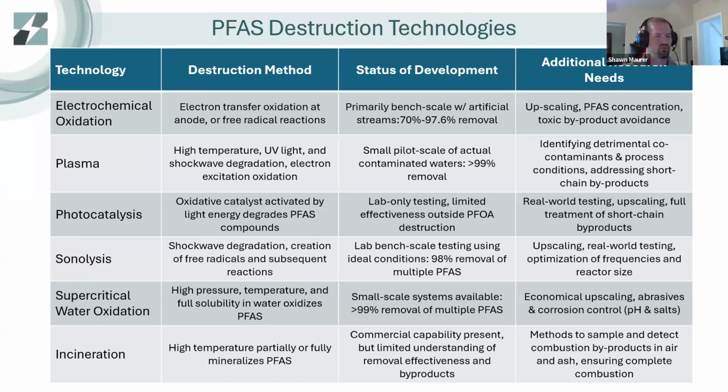There's two companies I'm aware of that provide supercritical water oxidation. Comes in essentially a 40-foot cargo container, pre-built to do energy recovery and things like that. So once you start the system up, it can be self-sustaining. You get better than 99% removal of PFAS. And your byproducts are essentially non-hazardous gases like carbon dioxide, nitrogen, and then mineral salts. The chlorides recombine to create chlorine salts, table salt, things like that.